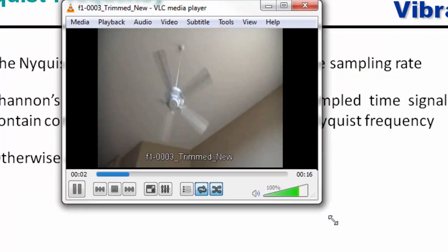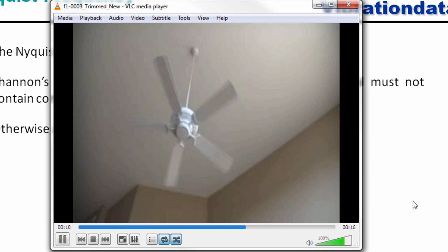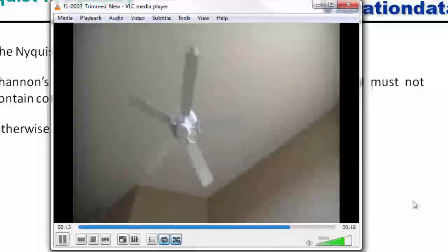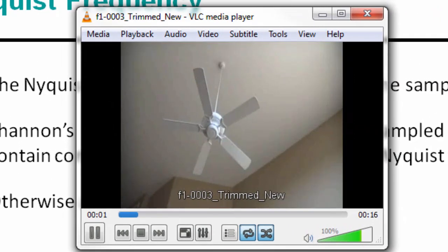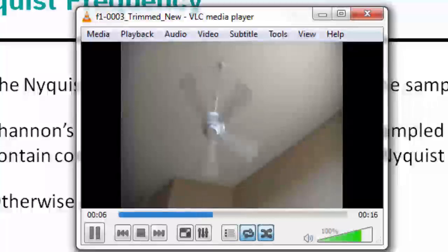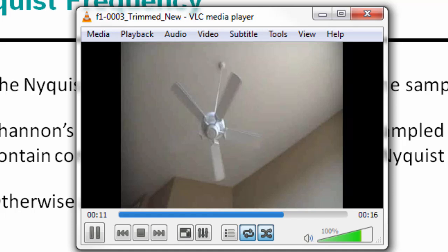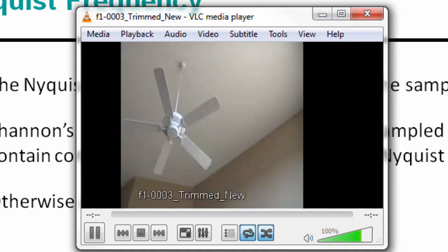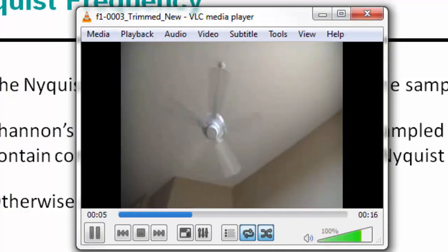Well, that's all, of course, kind of a funny joke, because what we really have is aliasing going on. We have optical aliasing going on because the frame rate is too low to adequately capture the motion. And as we look from top to bottom, the ceiling fan was always going counterclockwise. But just as an optical illusion, in some cases it looked to be going clockwise. And just another piece of the puzzle here, what I did is I actually ramped the ceiling fan up to a steady speed, then almost immediately ramped it back down.